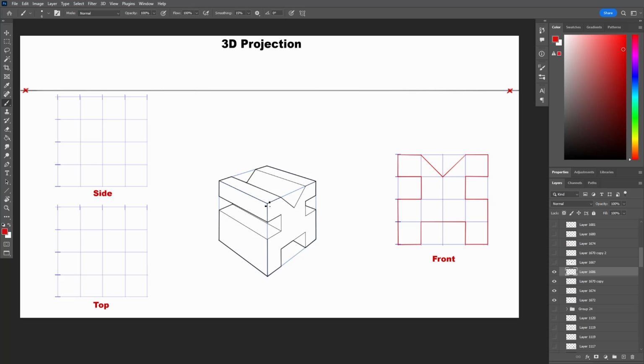The side view has a 1 unit rectangle in the top, 1 unit as a whole, and 2 units for the body. But there's also a hole in between the top and the legs. But the top hole is on the same line as the top rectangle, so it won't show up in this projection. But the bottom one is in between the 2 unit long leg, so it will show up in the middle as a dotted line. The hidden holes or spaces won't show if they are on the same line that shows on the side view. It will only show in between the side lines.